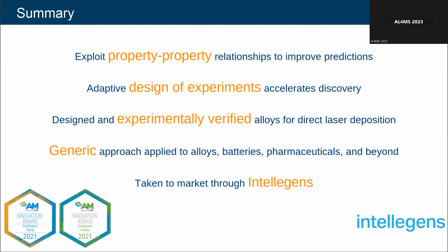Yeah, so the function is definitely rather complex. These alloy spaces tend to undergo a lot of phase transitions. In the first example I showed you, we made a two-phase alloy, a gamma-gamma prime alloy, but there were another 58 phases that could form in this alloy that we wanted to avoid, and there were two in particular that you really want to avoid.